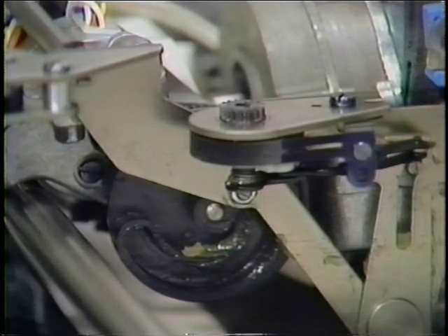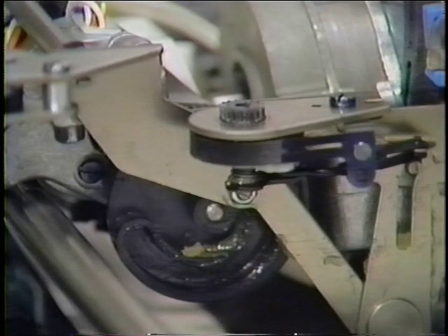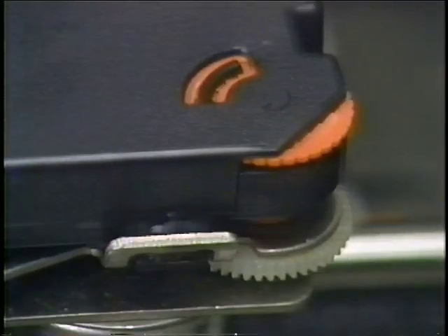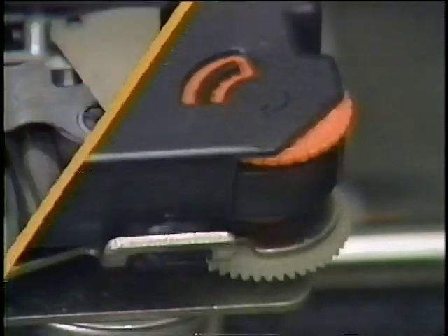After a character prints, if there are no other characters to be printed, the lift motor drives the lift cam back to the home position. The ribbon feed motor feeds the ribbon immediately after the character prints.